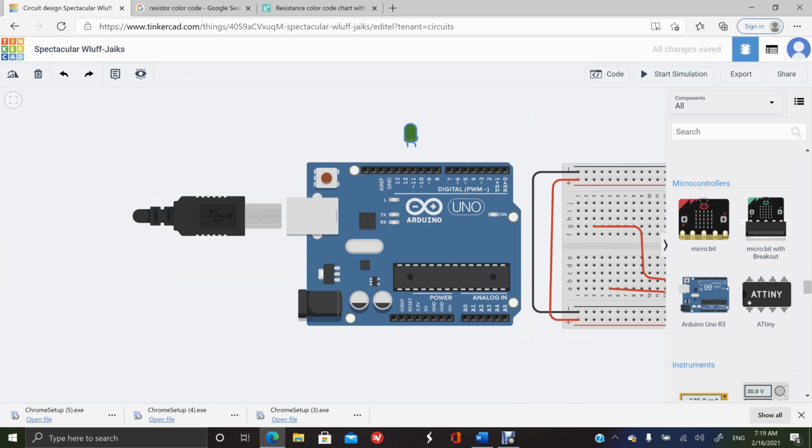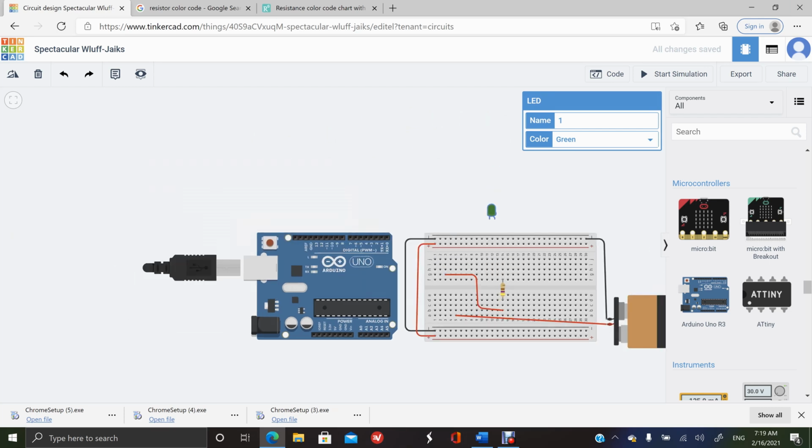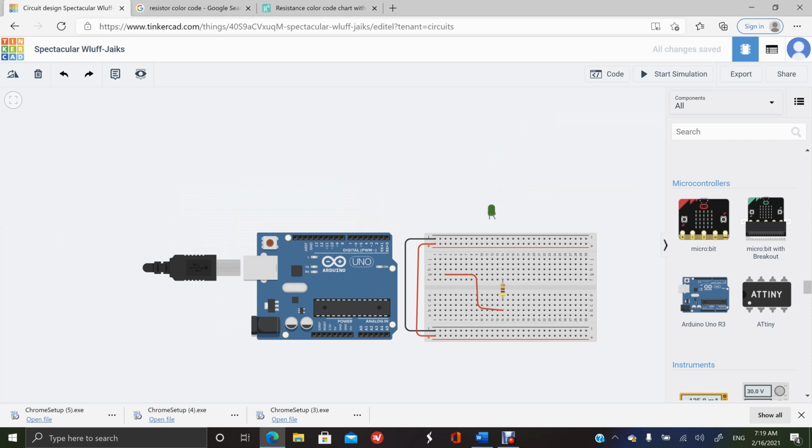Okay, now we're going to build. We're not going to use pin 13. We're going to use a different pin, but this time, instead of having the LED plugged into our Arduino, we're going to have this LED in our breadboard, and then we're going to provide that signal to our LEDs. So we don't need a battery, because that's going to be provided by the Arduino.